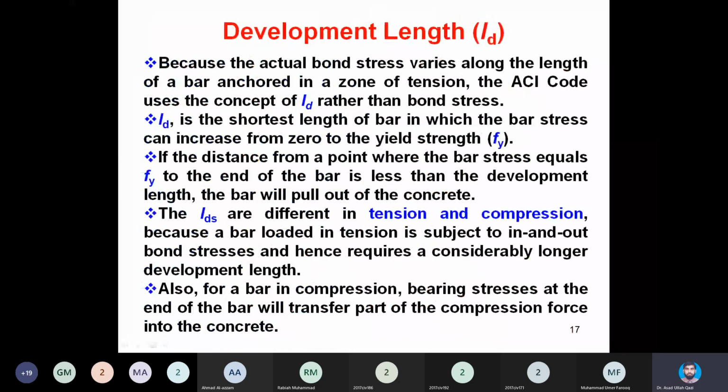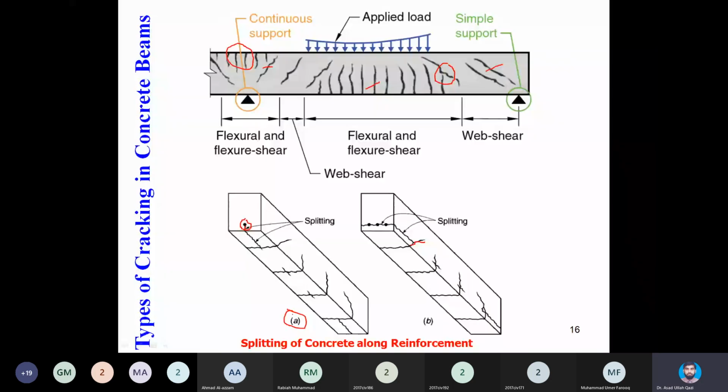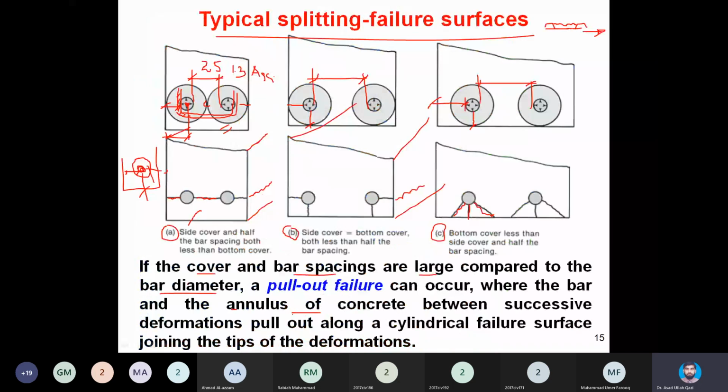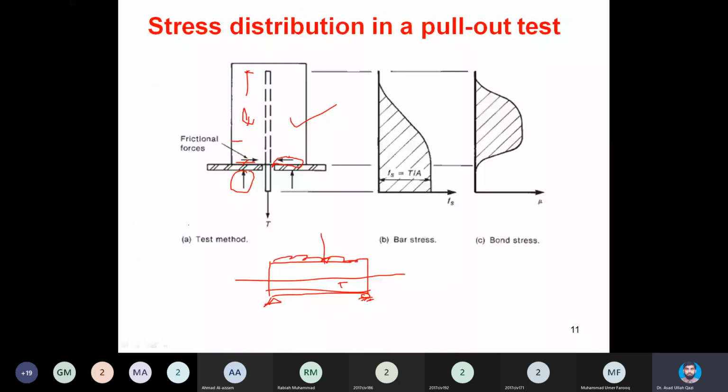Now we learned, based on the pull-out test, that we have the opportunity, on that simple pull-out test, if I am putting the bar in the jaws of the machine, gripping the bar in the jaws of the machine and applying load on that bar, I can note down at what load this bar is pulled out and the needle stopped, and then I can use my simple equilibrium equation to calculate either the bond stress, or against a certain load I can calculate what length I require to hold that force.